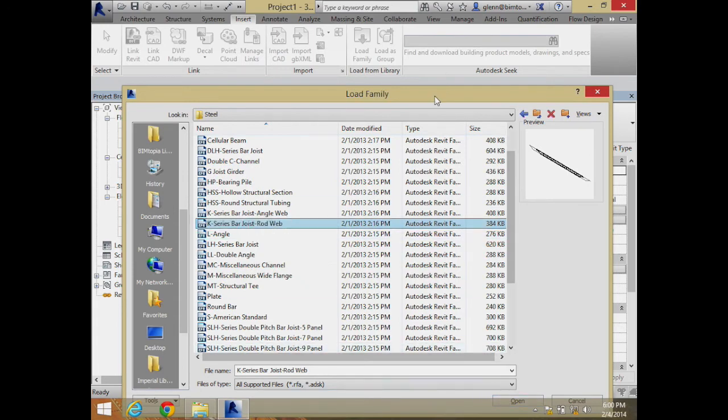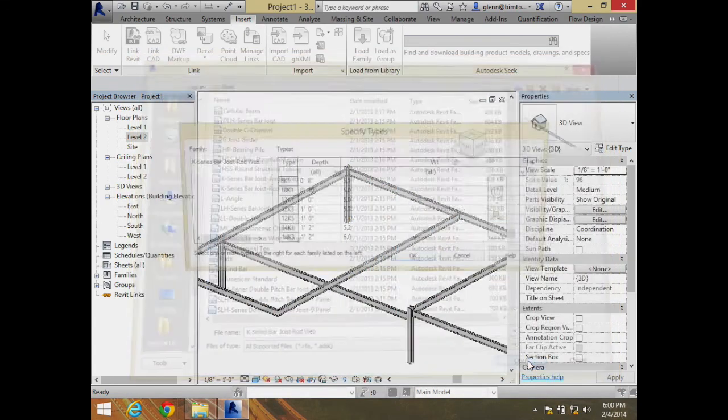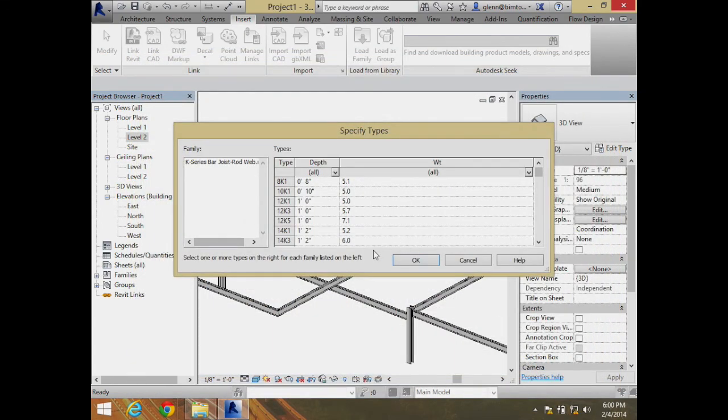You open it up. They have sizes, just like all the beams do. The sizes are rated very much like the beams in terms of the first number being the depth, so whether it's 14 inches, 16 inches, 18 inches. The second number after the K, that's kind of the thickness. It's actually the stiffness. It's really how hefty that is, the weight per lineal foot.